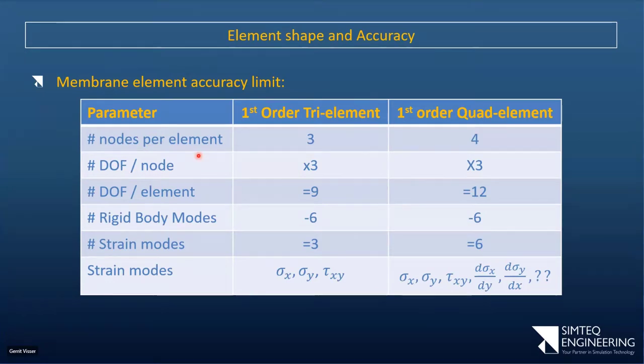And in this case, by going through this, there was just enough information to be able to calculate a constant stress in X, constant stress in Y, and a constant shear over the whole element. Compared to a first order quad element that only has 1 additional node, we had all of those same constant terms, but we could also calculate gradients of stress.